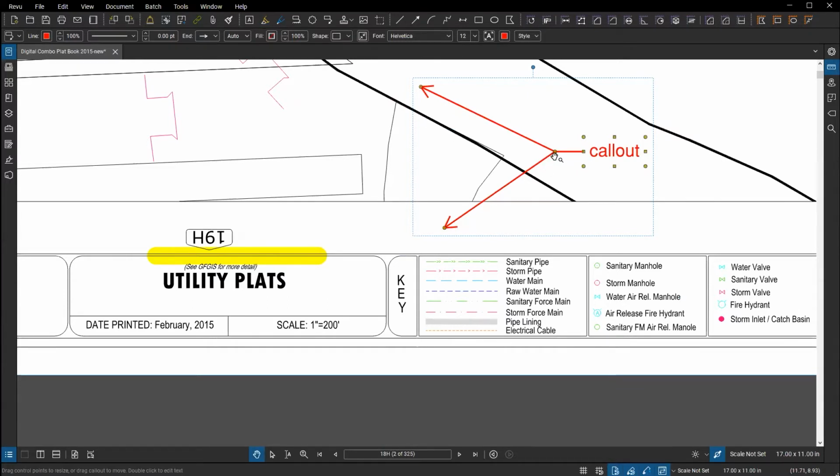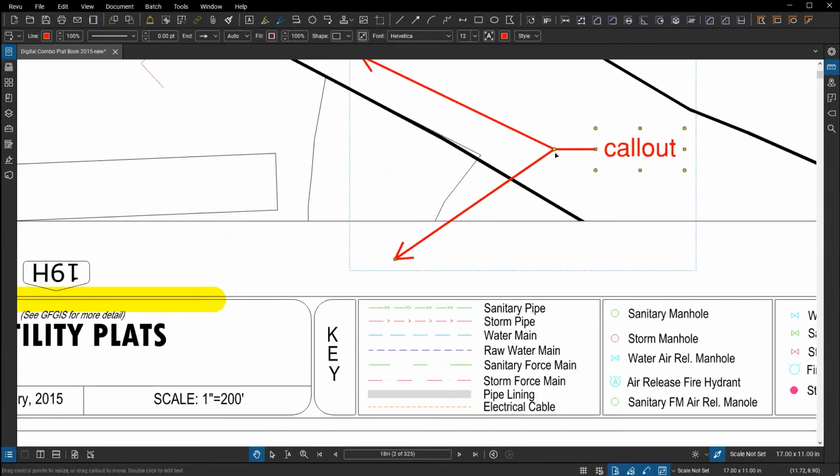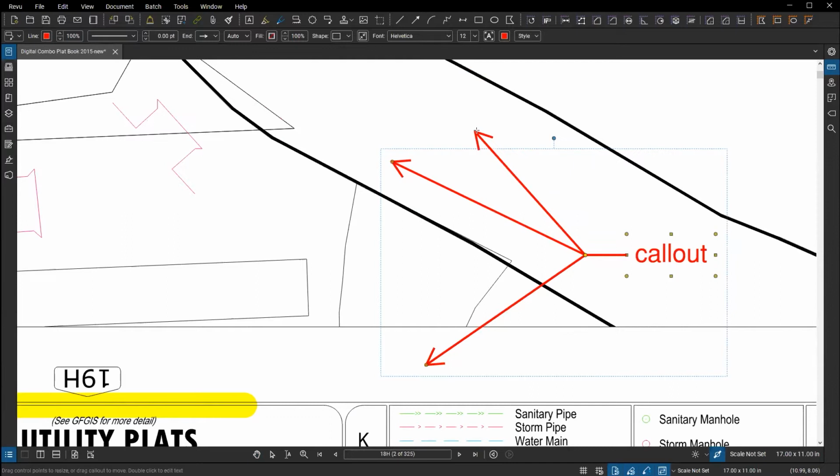So if you hold down shift, you go near this little kind of corner point, that transition to have. If you hold down shift, it may be hard to see on screen, but it's a little plus in the lower right-hand corner of the arrow I have in my cursor. That's a plus just means if I pick there, it's going to add in an additional leader off of the callout. So shift, pick. You can then let go of the shift at that point, and I can drop that arrow in however it needs to be placed onto my file. So if you want to have one note with arrows pointing across to multiple different destinations to it, you can drop those in.